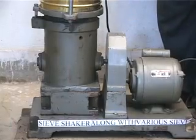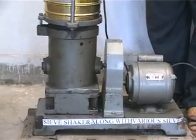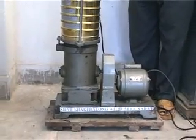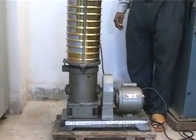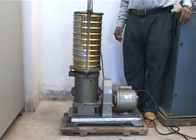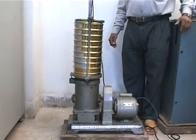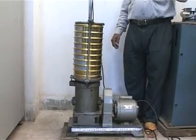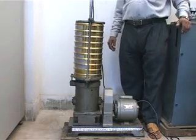Now you see that we have put the sieve set, on which we took 500 grams of soil sample, on the mechanical shaker, and we are going to subject it to mechanical shaking for about 10 minutes. After that, we are going to find out the weight of soil retained on each individual sieve, and from that we will construct the grain size distribution curve. So we'll start the shaking now. You just watch it, and then we are going to come back to it.